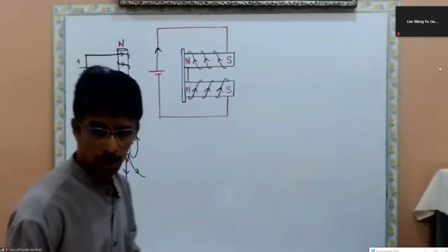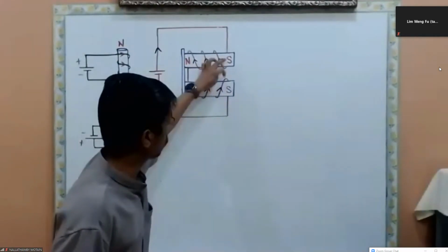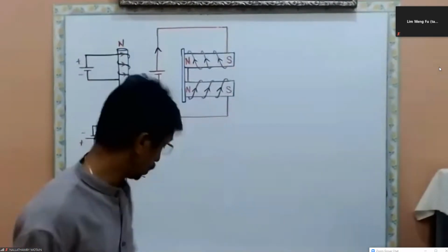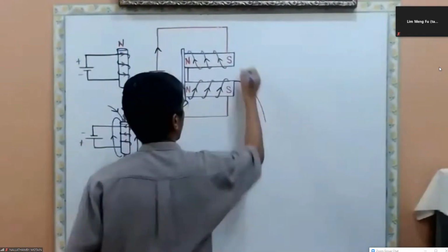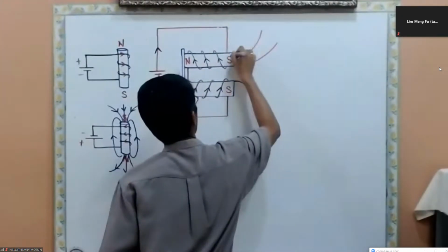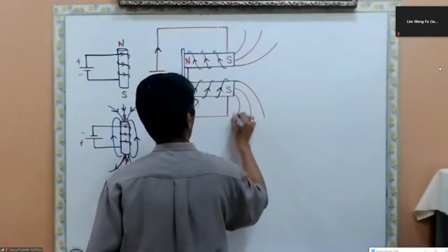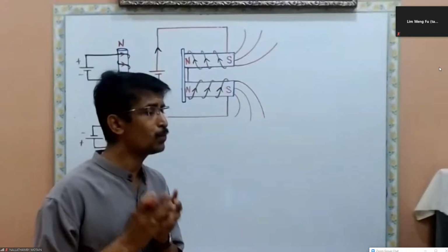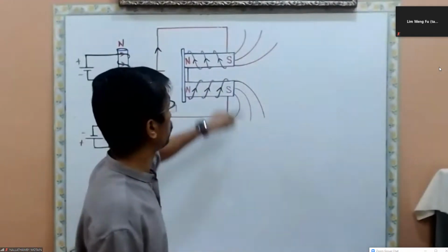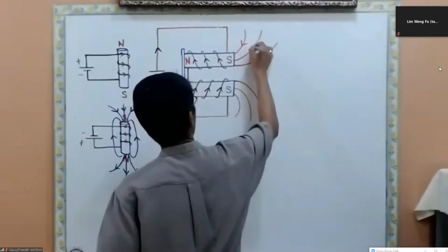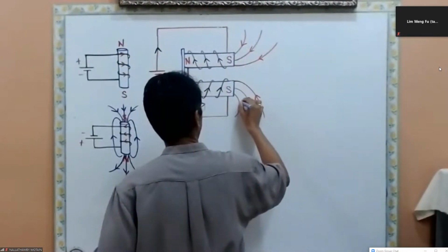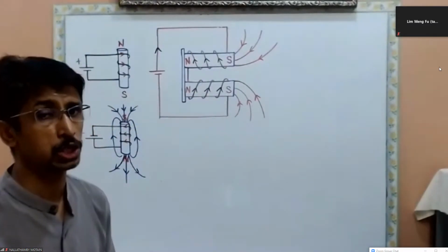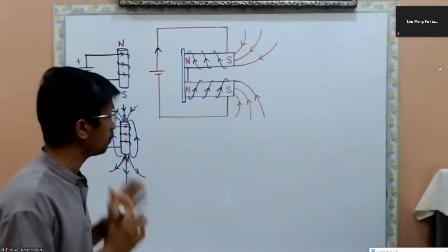So now you can see at the end over here, south and south. They are like poles. If like poles, we know that it will repel. So if repel, the magnetic field will be away, getting weaker. It produces a very weak electromagnet because it produces like poles. So it is not suitable. If you wind as given over here, it won't produce a stronger electromagnet.